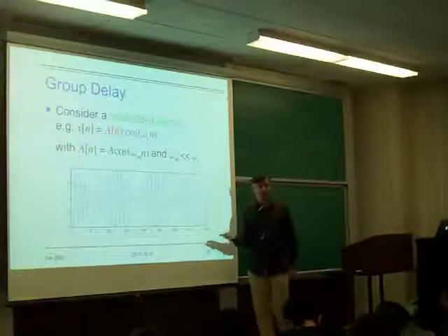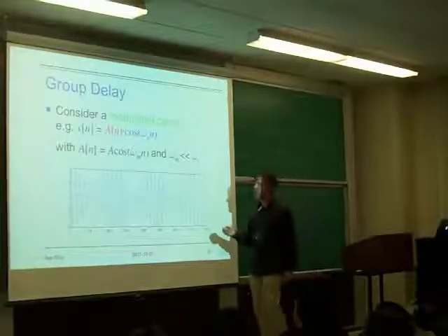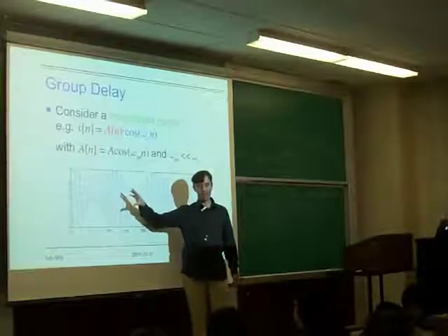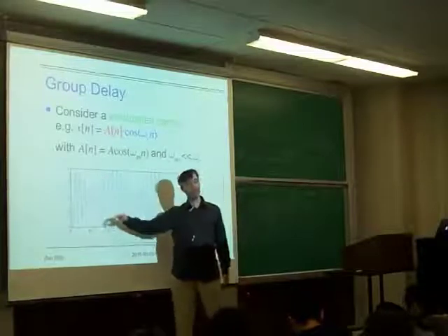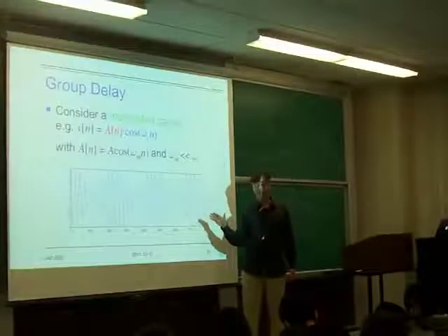The other kind of delay is this thing called group delay, and that is about not so much the delay of the fine structure sinusoid, but the delay of the envelope of a modulated carrier, because it turns out that that can be something separate and something interesting.